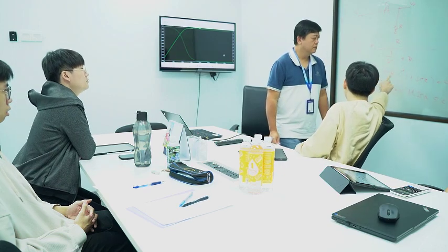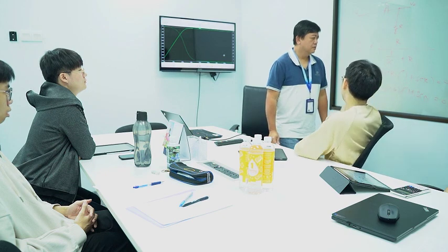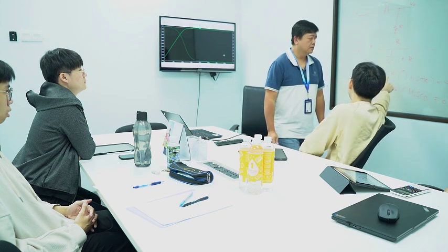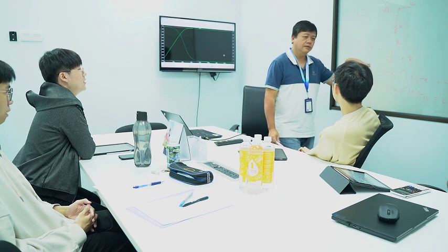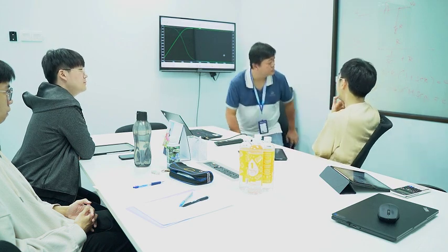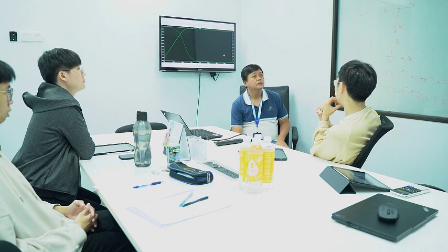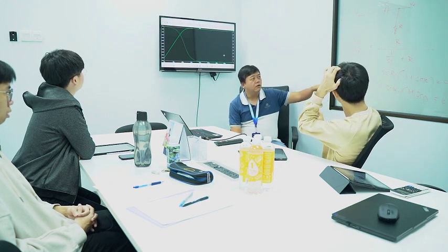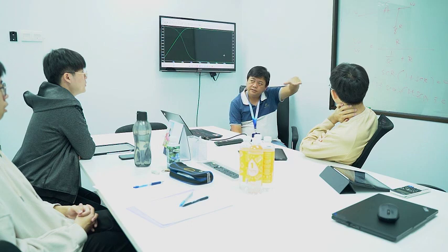Without this one, with just this, the phase should also start 1 decade earlier. But this one should be starting at the origin, at 0 frequency. So the phase for an origin pole starts at 90 degrees first.